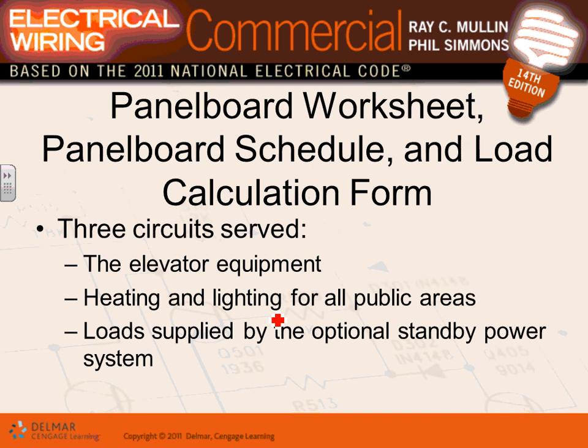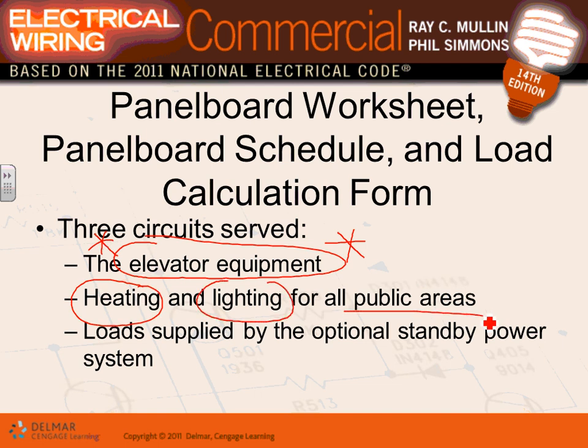Okay, 3 circuits served. We also have elevator equipment that needs to be powered. So we have a circuit that's going to the elevator. You can't charge the elevator circuit to Karen's tenant, right? Because she is not the only one who's using it. So that's a common area. Heating and cooling, especially heating. So here's another, heating, lighting in common areas or public areas, they call it. All these loads, so I have 1 type of load, 2 types of loads, 3 types of loads, with a couple of other receptacles, guys. They will be fed from a common panel, house panel. I cannot emphasize it enough, common panel, house panel.